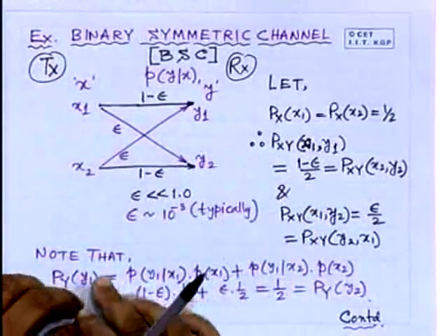So for the same pulse at the same bit rate, the pulse shape becomes more and more rounded, which means the pulse energy goes into the subsequent bits, and the channel is now exhibiting memory. We are not talking about that kind of channel. Our starting assumption is that the channel is memoryless.